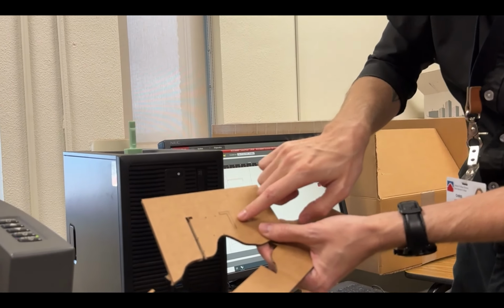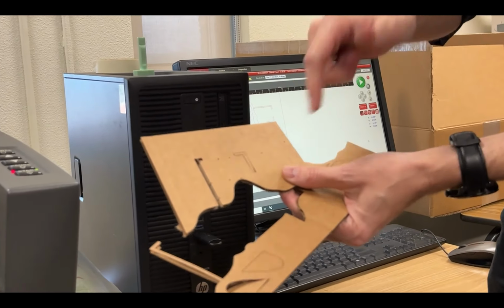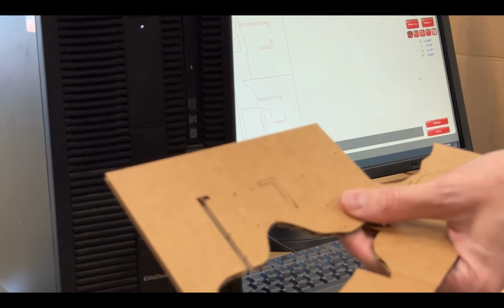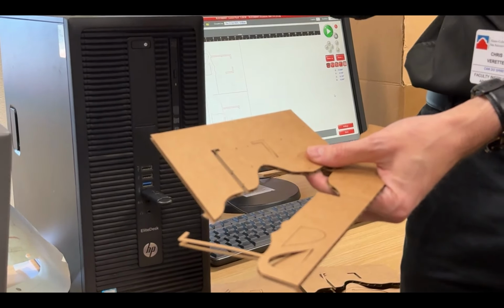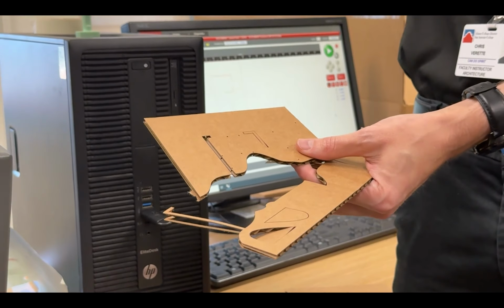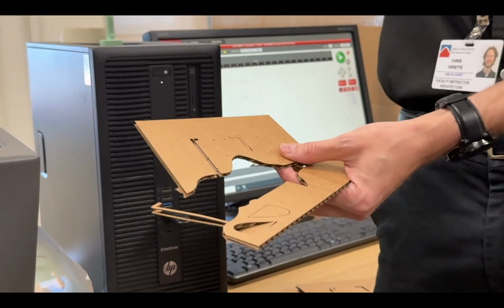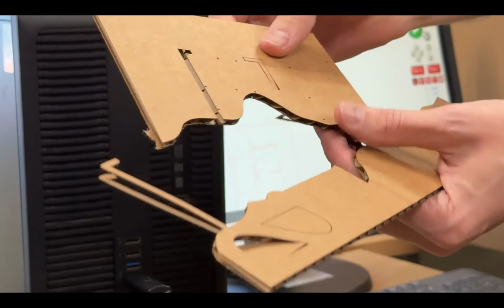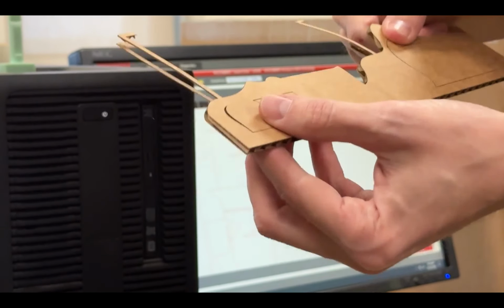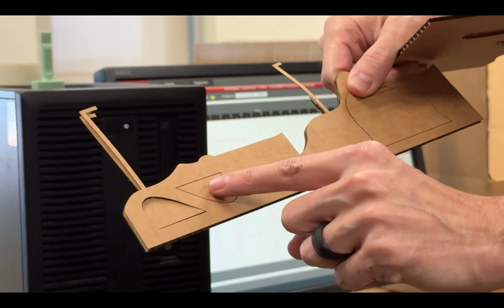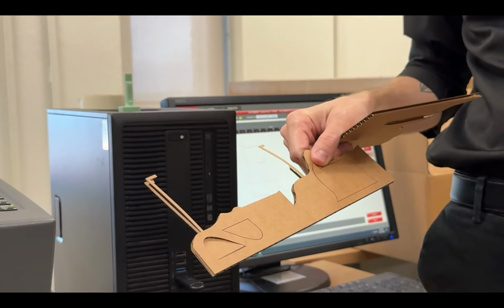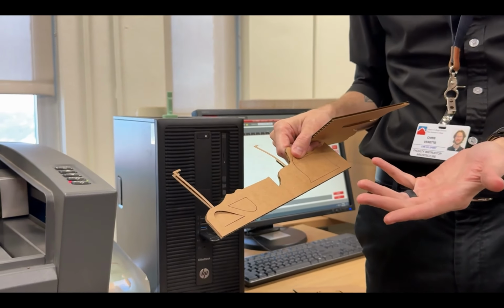Another thing to keep in mind, guys, is look how thin these lines are. That's actually what you want. That means we had a good ratio of that cone. If it's too thick, that means you got a big portion of that cone, right? Whether that was too close or too far away, right? So I definitely want to point that out. Because some of these things you can kind of just tell. I mean, that's a beautiful cut. It's very clear that they just repaired this and they just cleaned it really well, right?